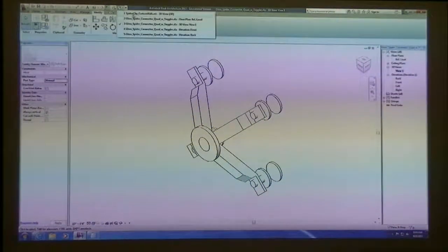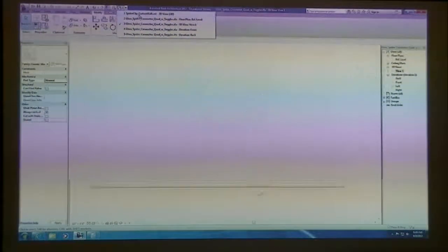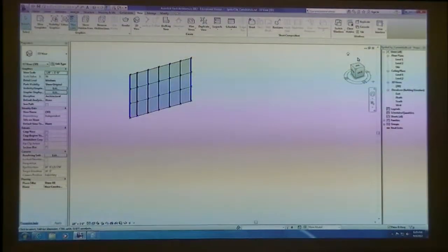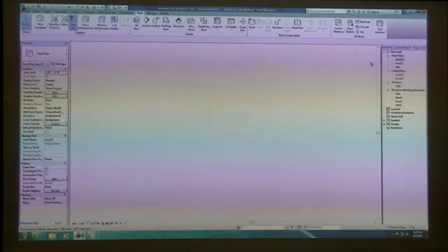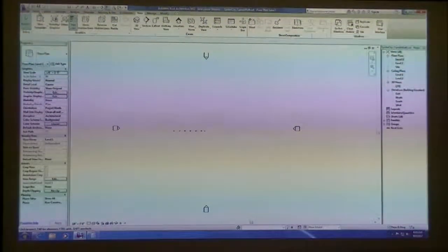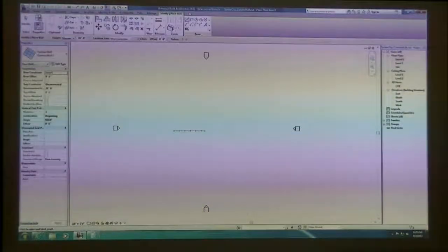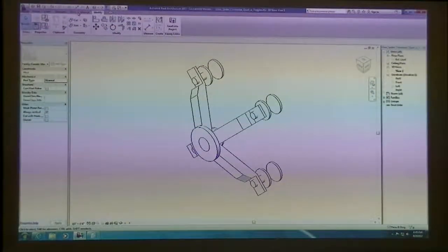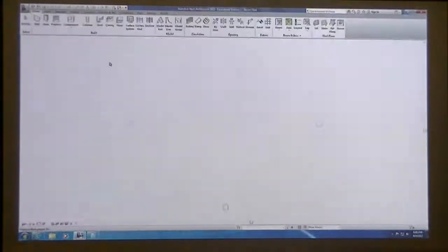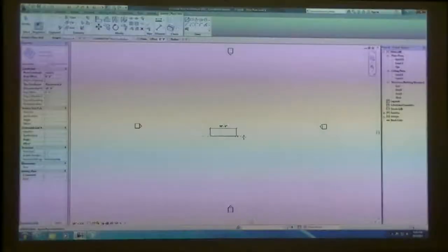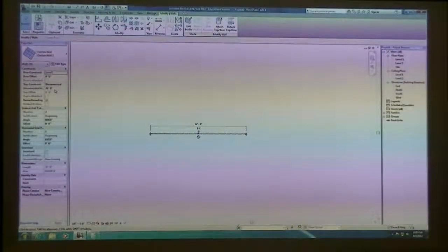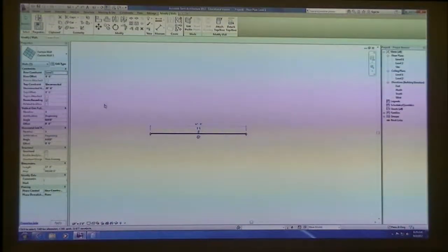The next thing I want to do is go back into a project file. So you might want to just start a new project file, or you can work off to the side in your hotel unit. But I'm just going to be working in a typical new project. And in level 1 or wherever you're going to work, just go ahead and draw under home, wall, and let's draw a curtain wall. I should probably start a new file. So just using the basic default curtain wall, let's draw curtain wall 1 and draw a sheet of glass. Doesn't matter the length, but give it some length, like at least 30 feet. And we can make sure that by default it's already 20 feet high. You can make it something like 20 feet high or at least something greater than 10.